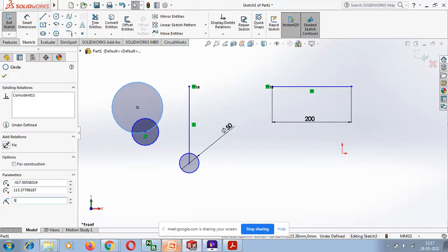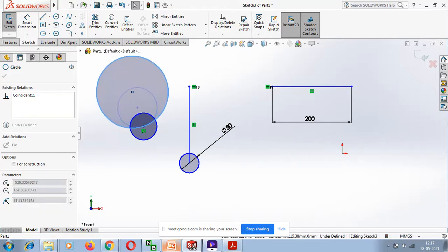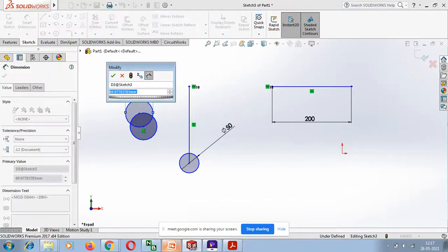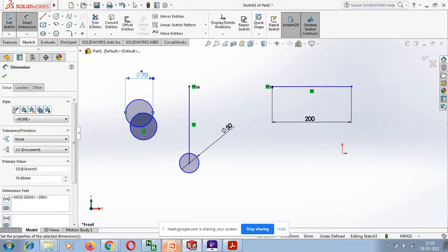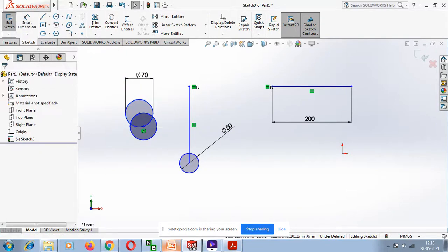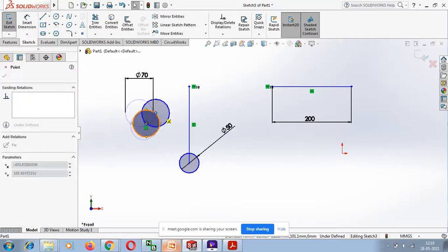But even if I make this change here, okay, still it is susceptible to changes. So unless I put a constraint on it, if I constrain, it becomes a fixed value. Okay, now it will not change. So you can see that the value is not changed.